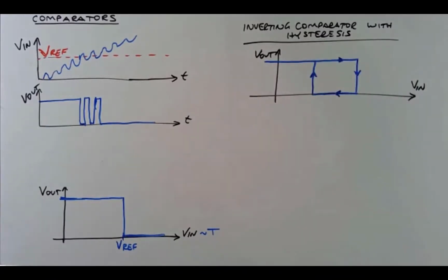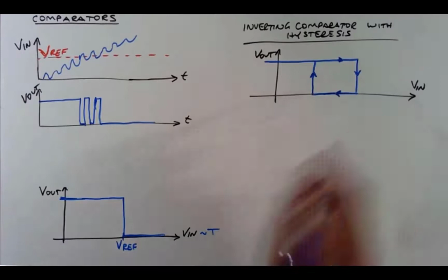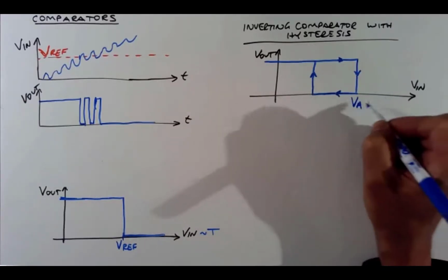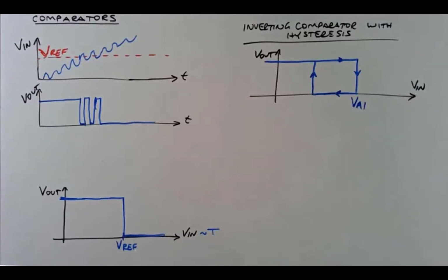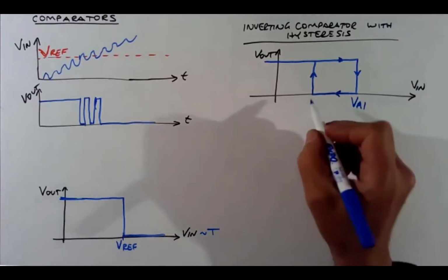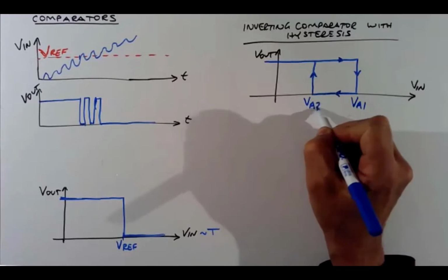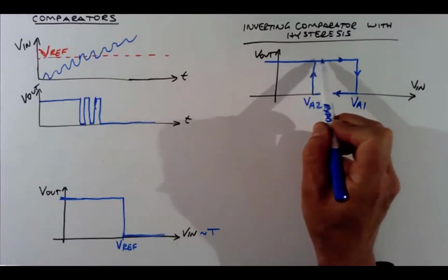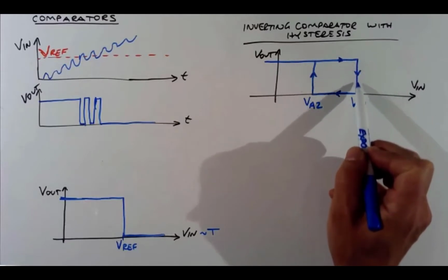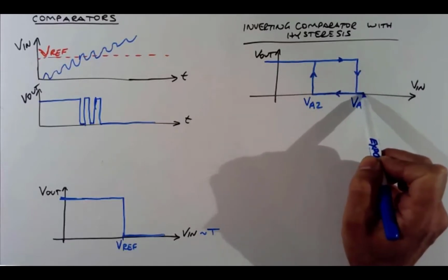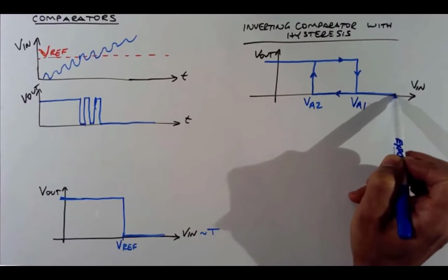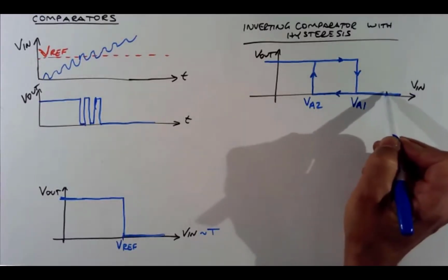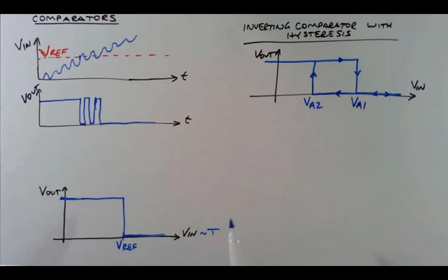Right? So this is implying 2 thresholds. I'm going to call that threshold VA, and VA1 is this upper threshold, and VA2 is this lower threshold. In fact, the house was cold, the house heated up, got warm enough, heater turned off. It's one of those Colorado days. You could actually have the house heat up from external sources, the sun. So the temperature can move like that.